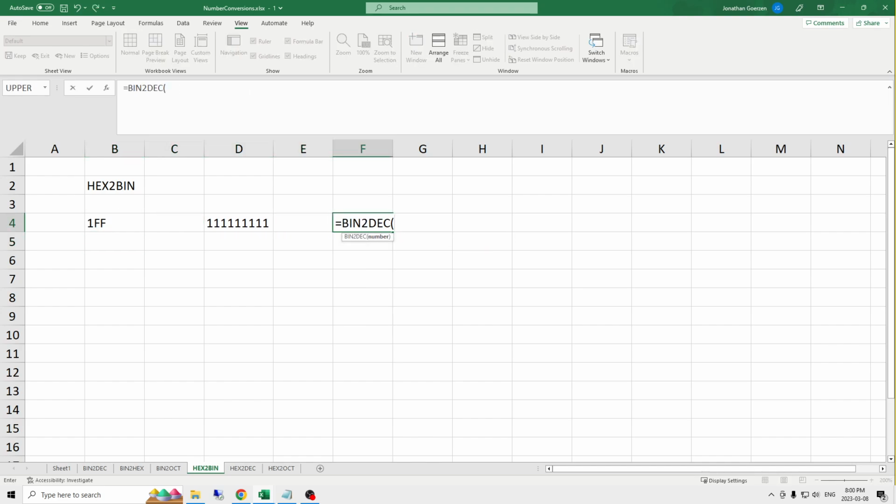If I take this output value and just convert it back to decimal, see that that's 511, which is what I hope I said the first time and not 512. 512 is incorrect. The smallest value, again, because it's using 2's complement in order to represent negative values, and it has 1 bit for counting or measuring positive or negative.